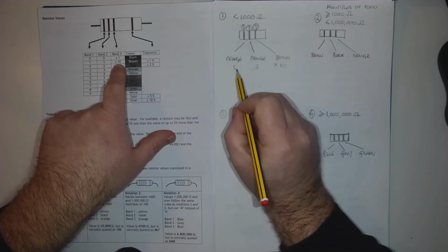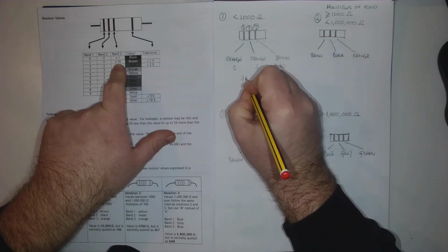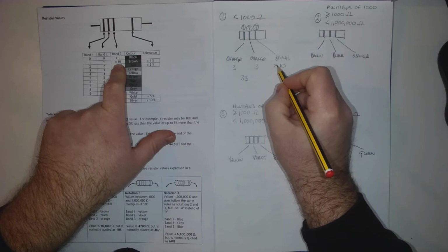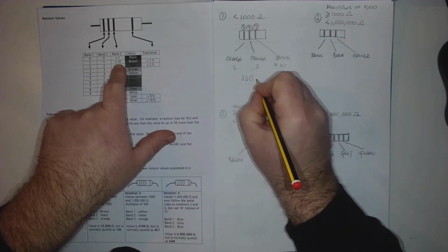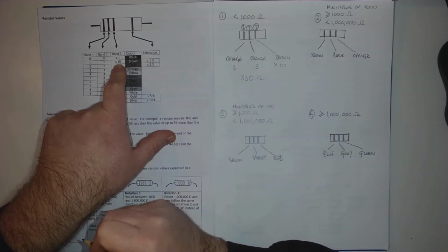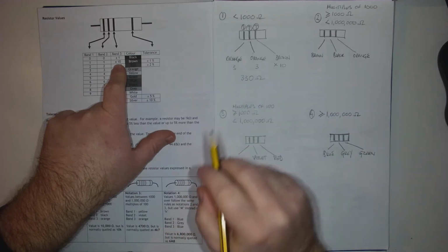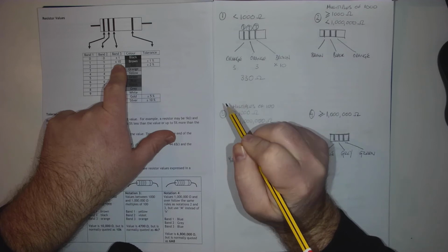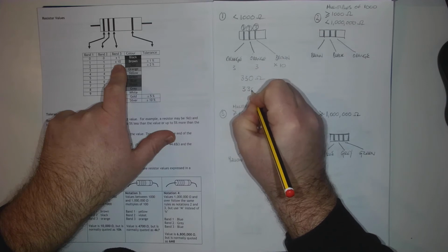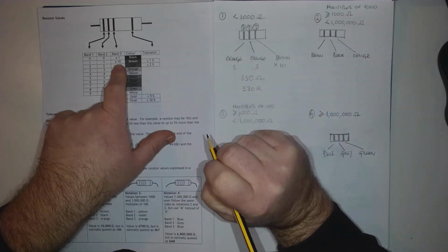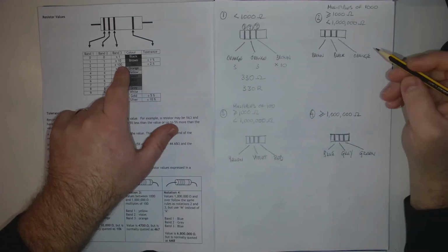Now what that means is that if we take the 2 3's together and read them as 33, and we multiply the 33 by 10, we get 330, and the resistor value is 330 ohms. And this is how we would normally write the numbers in engineering science, but in the real world, if you were to try to buy one of these resistors, you wouldn't ask for a 330 ohm resistor. We would use a slightly different way of representing that value, which is 330R. So this is real world, but the top value is the value that we would normally use in engineering science.